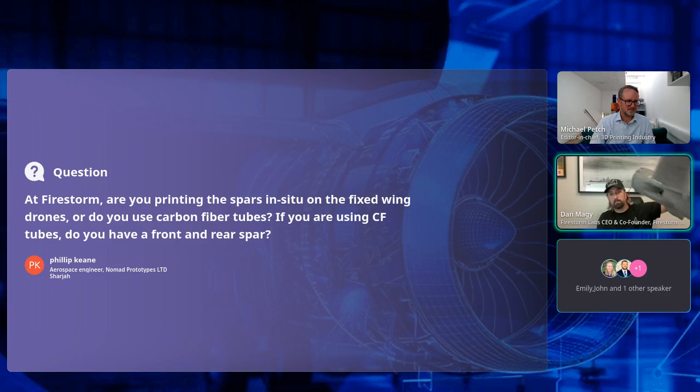But here's our empennage I was telling you guys about, where we basically have this quad intake here. There's no support structure here. This is just printed nylon 12. It's quite incredible. And then we've designed it so you can see here where it interlocks together, so they click together like Legos. It's really one of the cool things that allows us to build and scale.